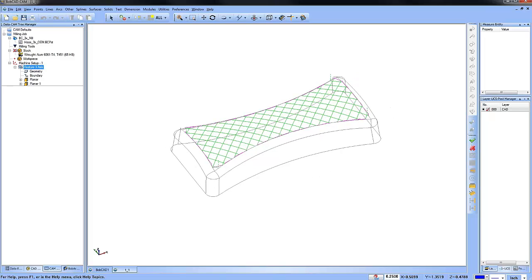So that's the first one that we were talking about, using planar on a 45. Then we use planar again on a -45. That gives us our crisscross pattern. We're using negative allowance in order to cut deeper into the part. We're going to use our step over in order to control the width of the pattern that we're creating. Okay, so hopefully that makes sense to everybody.